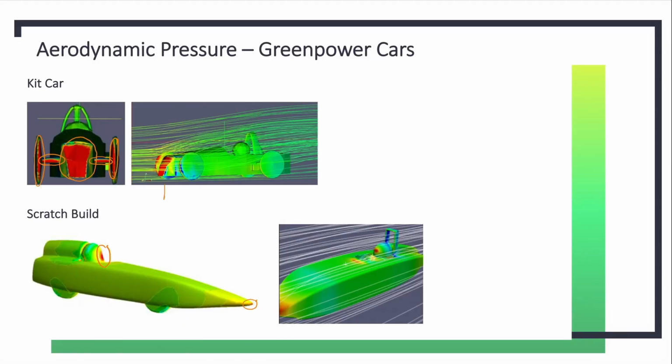you can see here that we go from red to blue really quickly. And that's an indication, the blue is an indication of flow separation, which means that you don't have a very good shape around that front. And in fact, the air can't stay attached to it and it just becomes separated. The fact that it goes green afterwards here means that you might have a bit of flow reattachment. But the first thing you could do is have a look at trying to smooth some of that nose out.